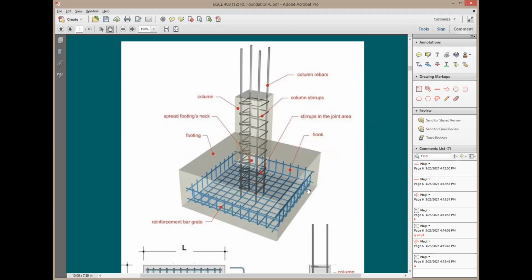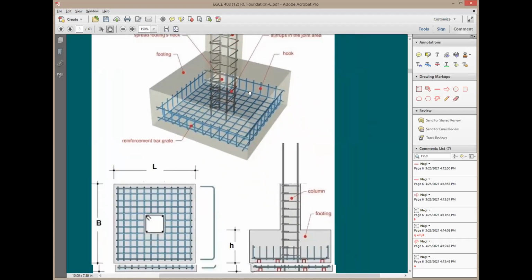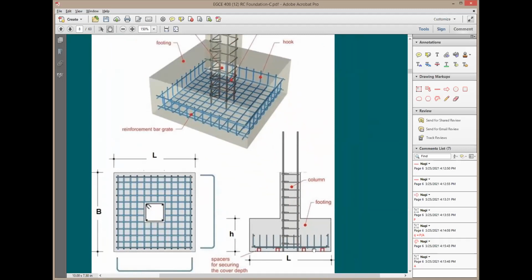And then we have also reinforcing bars in the footing in both directions. And as you see here, the reinforcing bar looks like a U shape. And you see this goes in both directions. In the plan view, you're going to see the rebars running in both directions. And of course, in this area here, the rebars are going to be running below it. It's just shown here as this light or white area, just to be able to show the reinforcing bars of the column, right? But in reality, all of these bars are going to be continuous rebars.